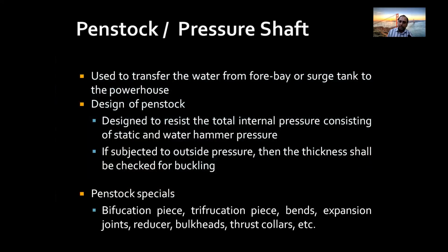It is used to transfer the water from the surge tank to the powerhouse. The penstocks are designed to resist the total internal pressure consisting of static plus water hammer. So if you are designing for the worst case, meaning the static water pressure plus the water hammer, it will always be safe for static minus water hammer pressure.